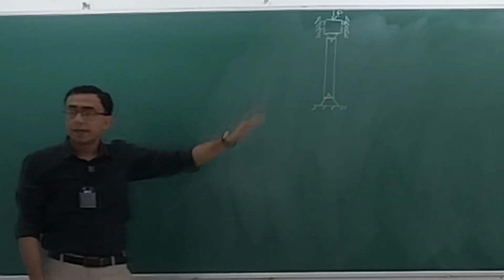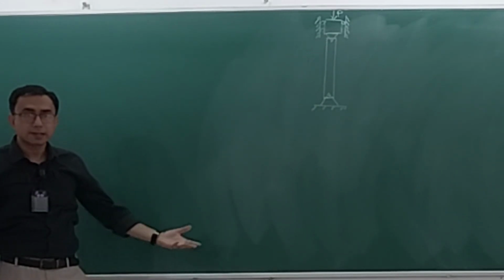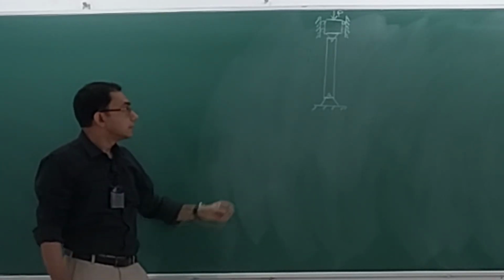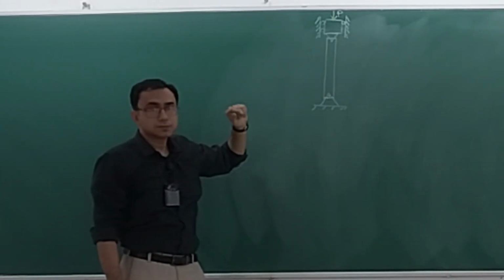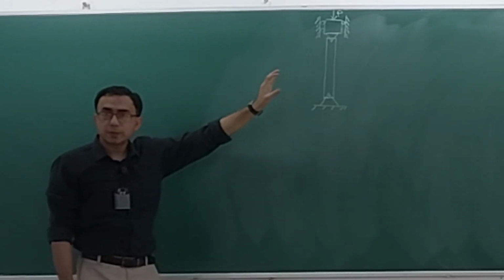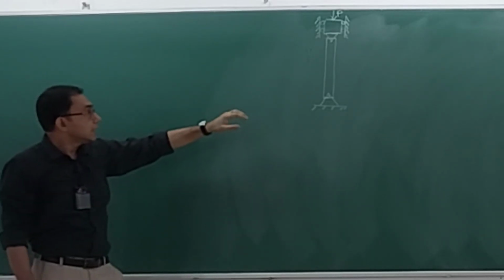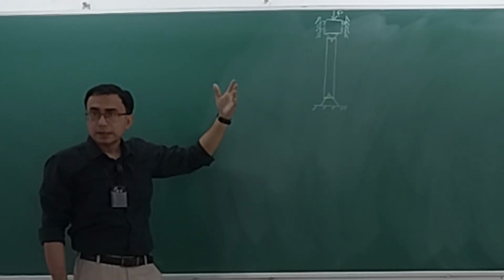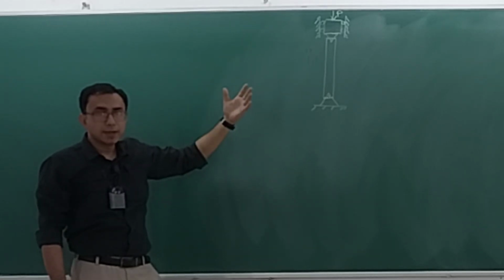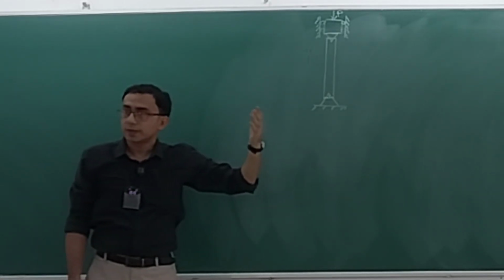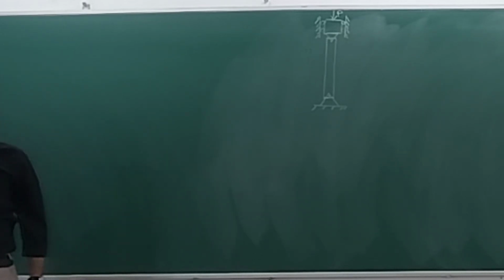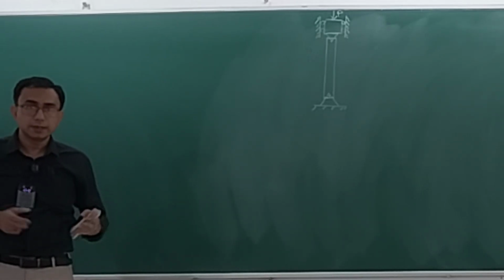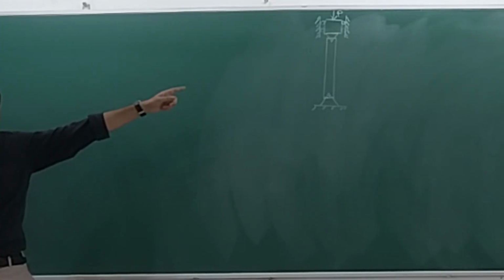Just like in our tutorial sheet 0, just axial deformation. But now suppose that there is a little bit of a disturbance. Suppose I poke it over here, through a very, very small force. What will happen is that it will get deflected. You know this. Now when it gets deflected, whether that is stable or not, that is what we want to investigate. When I was holding the plastic ruler between my hands and pressing it down, it was effectively this kind of situation.